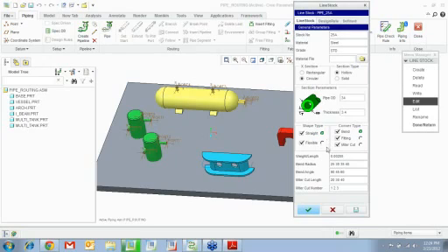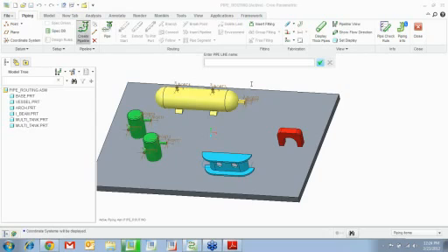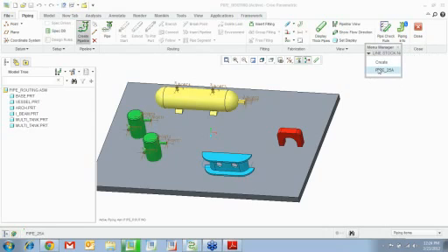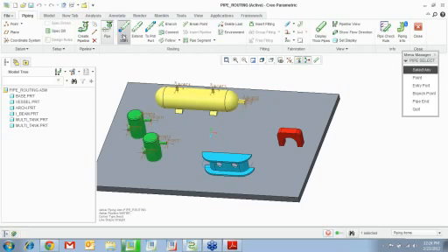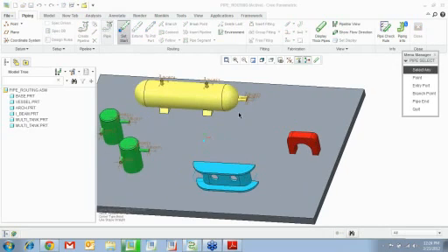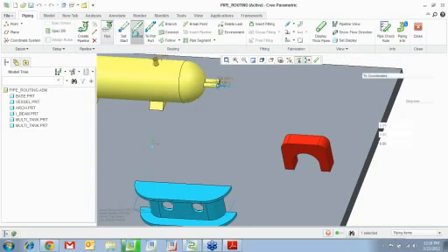All right. So notice it can be straight or flexible. By default, it is straight. So all this information is right there in the line stock. So now I'm going to create a pipeline. You give it a name, say water, hit enter. The line stock that I'm going to use is this. And now I want to start creating. So set start. I want to start from that port, and then I'm going to extend.